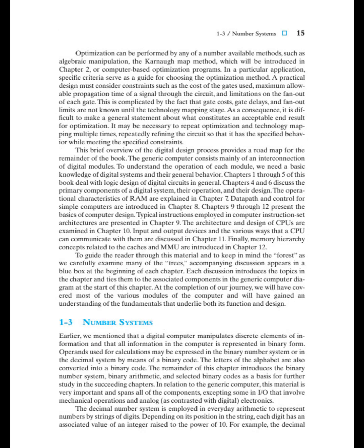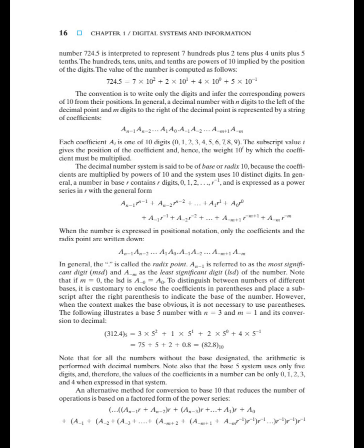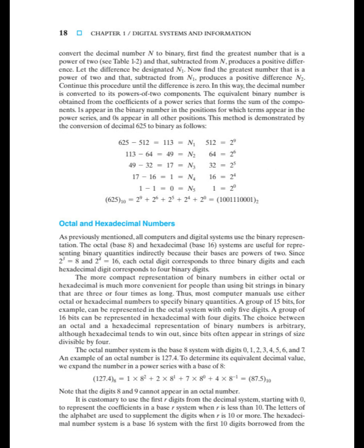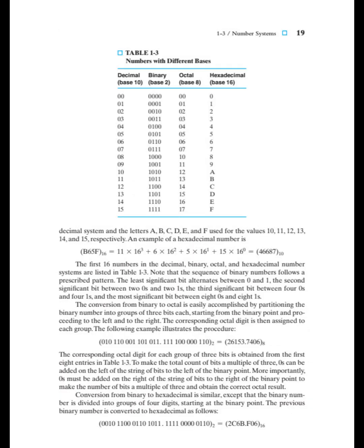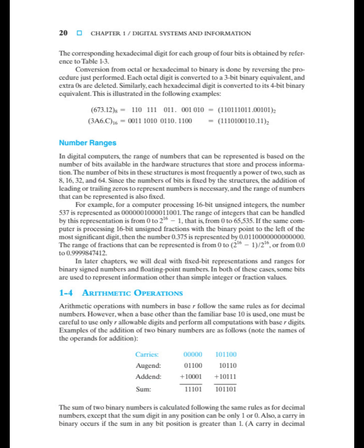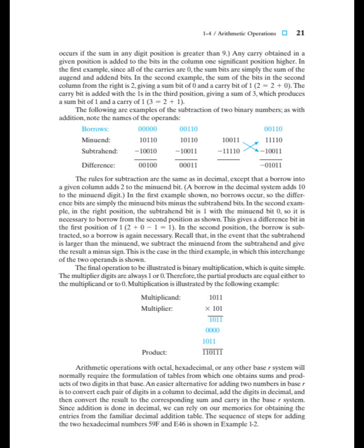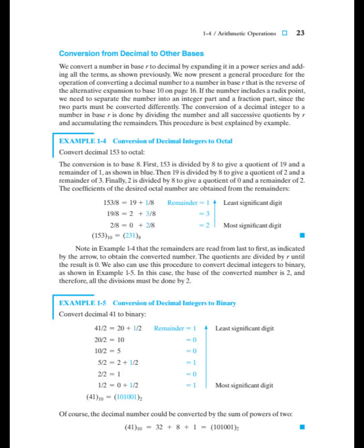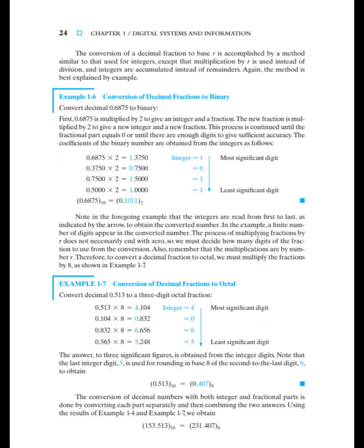Still continuous. Still continuous. Now, this voltage goes into an AD converter, an analog to digital converter. Okay. This chip takes that continuous voltage and turns it into a digital number. Binary, usually. So the smooth temperature reading becomes a series of distinct digital values. Exactly. If the AD converter has 8 bits of resolution, it might divide the temperature range into 256 distinct values. Interesting. This process going from continuous to discrete, that's called quantization. And there's a tiny bit of error there, quantization error, because a single digital value represents a small range of temperatures. The more bits, the more precise. Right. Smaller steps, higher precision.